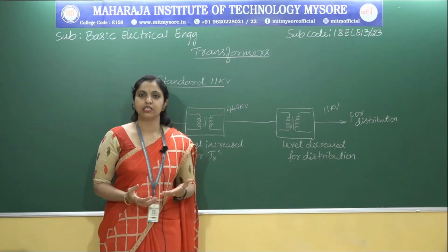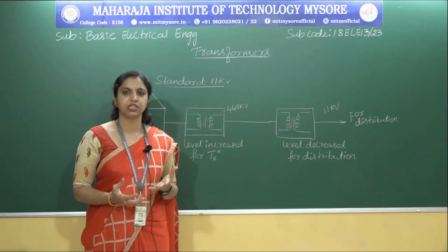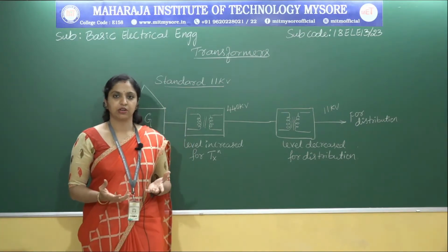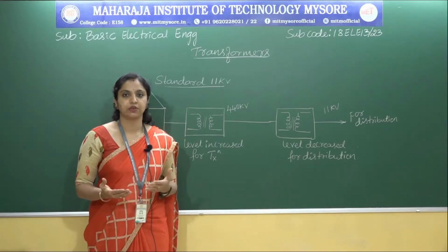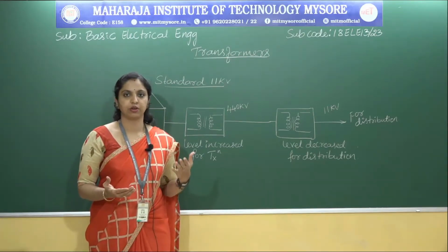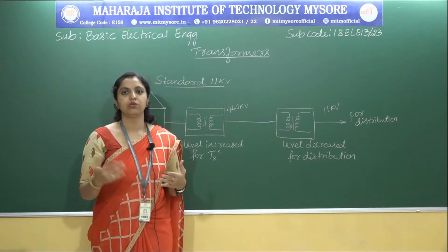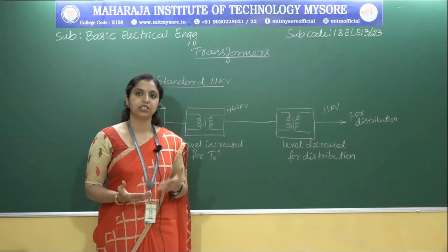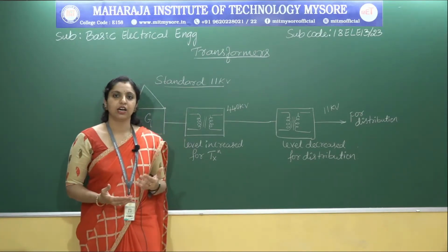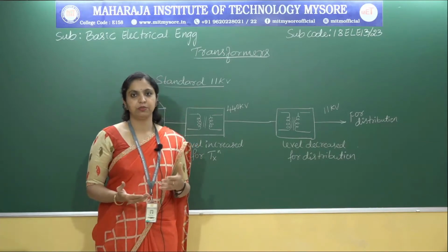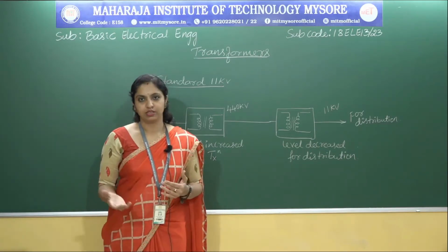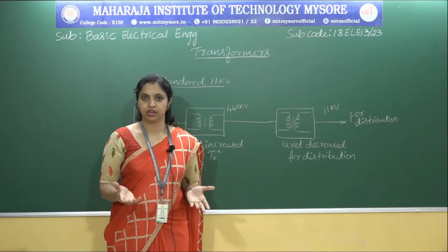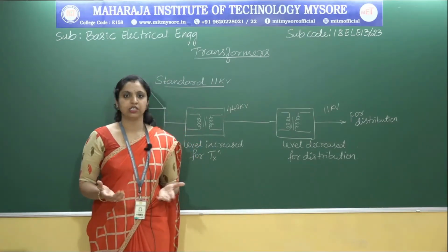A transformer is a static device by means of which electrical power is transformed from one AC circuit, that is, from one alternating current circuit, to another AC circuit with desired change in voltage and current, but without any change in the frequency.